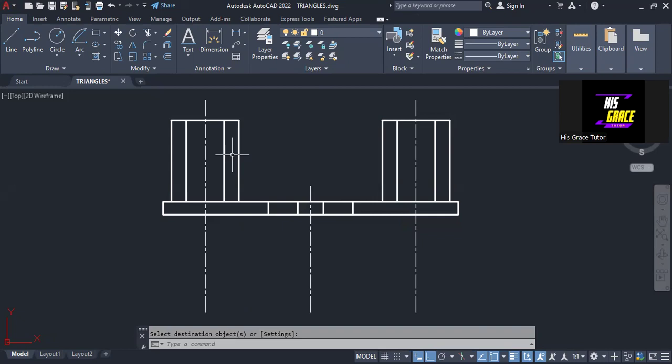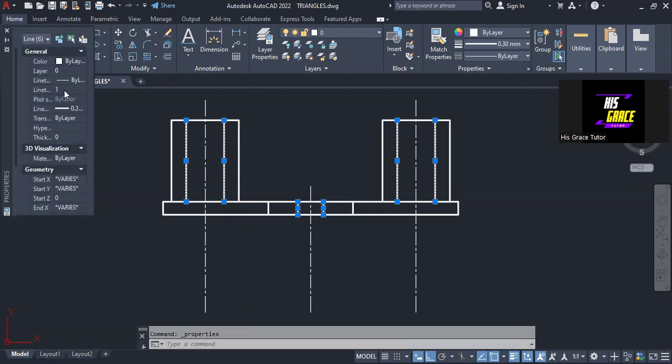But I can see that the lines are not really showing. So I'm going to change the property here. I will select each of them and make it 10. The thickness, or the line width, I'll make it 10 so that we can see the short dashes line. It may not work for this one, but let's see how it goes. So I'll select this and give it 10. Okay, so make it 10. So press the enter key. So I think it will show when we deselect.